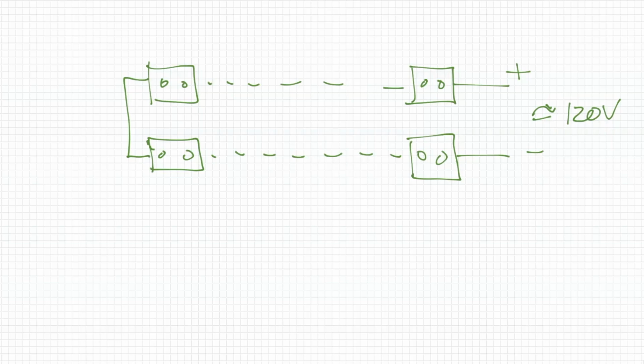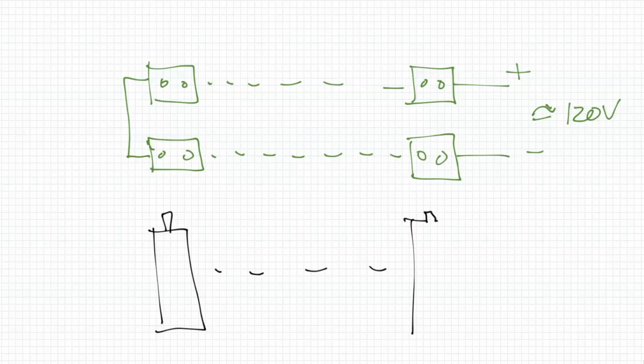Now, if you have a lead acid battery system, it will be potentially emitting hydrogen and oxygen, so there is an explosive risk within that enclosure. It's a requirement that you have ventilation. So I'm just going to draw an elevation view of these batteries. So here's the batteries in side view. All right, so here's our row of batteries in side view.